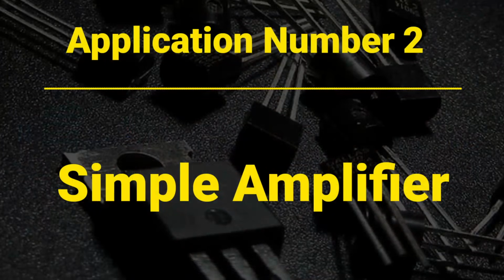Up until now, we considered the op-amp as a comparator. There is another usage of op-amps that is so exciting. Application number 2, using op-amps as a simple amplifier. One of the most common uses of op-amps is to use them as a simple amplifier, also called a non-inverting amplifier. The main job of an amplifier is to make tiny voltages higher for ease of processing or measurement.